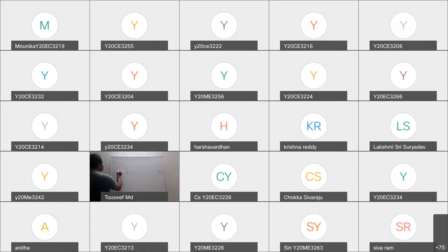Okay. So I know that A dash B dash is equal to 65. A dash is center, 65 as radius, draw an arc from the locus of B dash to obtain B dash. Now join A dash with B dash and extend A dash B dash up to here, so this becomes your VT, and if you extend some more up to XY, you will obtain some H. Okay.